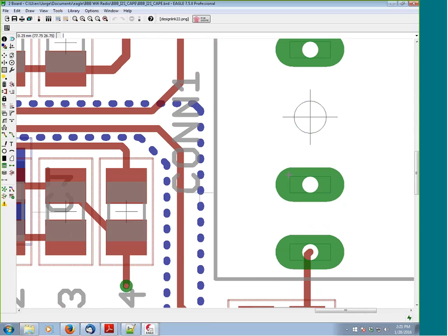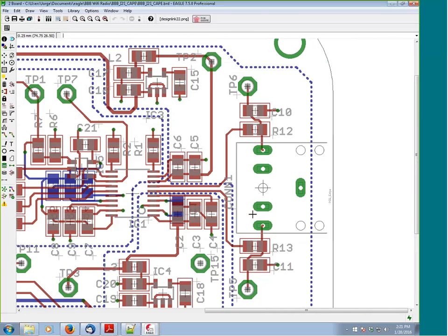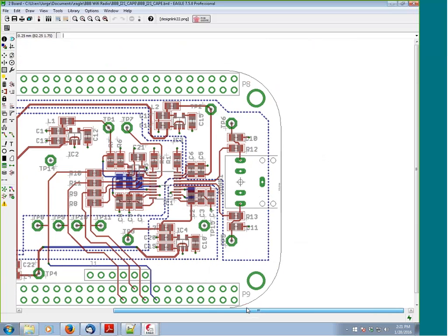When I went to generate the Gerbers, I made sure to put the information on layer 46 as its own Gerber, and I let the board house know that I needed that milled from the board. In doing so, I got the slotted effect. For future releases of Eagle, we want to have something a little bit more native, more internal to Eagle to be able to generate that.